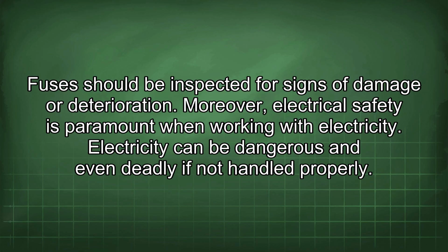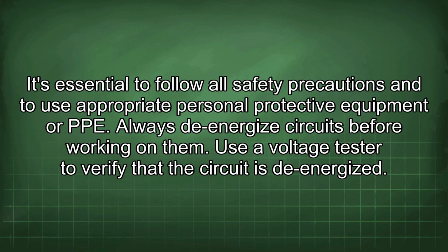Moreover, electrical safety is paramount when working with electricity. Electricity can be dangerous and even deadly if not handled properly. It's essential to follow all safety precautions and to use appropriate personal protective equipment, or PPE. Always de-energize circuits before working on them. Use a voltage tester to verify that the circuit is de-energized.